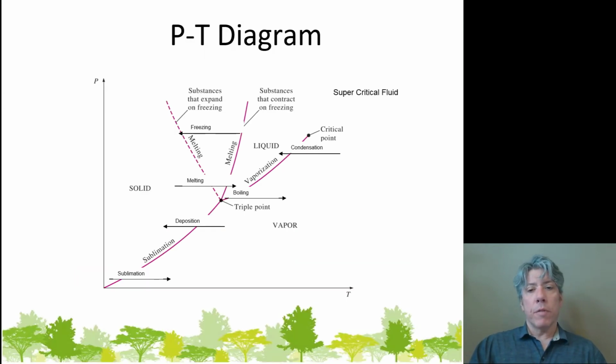Now, the pressure versus temperature diagram. I showed you a little bit of this before, where I was showing you the saturation pressure and temperature, but that was up on vaporization, from the triple point all the way up to the critical point. That was the section of the curve I was drawing. I actually didn't take it down to zero pressure. If we extend that diagram a little bit more to lower pressures and temperatures, then we can also see sublimation at relatively low pressures, where solid and vapor move back and forth by deposition and sublimation.